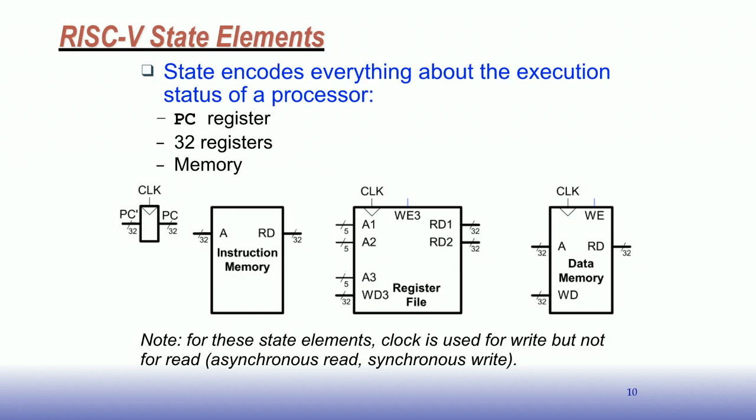So it's just a way to do a lookup. Think of it as a big multiplexer where you're multiplexing out some value to the output according to the control, the address. The other thing is the register file, which is probably the most complicated thing up here because there are multiple ports. In order for our processor to be efficient and run fast, we'd like to be able to read 2 register file values at once, and at the same time, within the same clock cycle, write a value back. You'll see this when we talk about the R-type arithmetic instructions. They'll take 2 operands from the register file, do some operation on them, and then return the result back to the register file. This should all happen in one clock cycle.